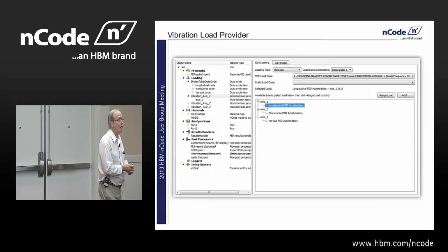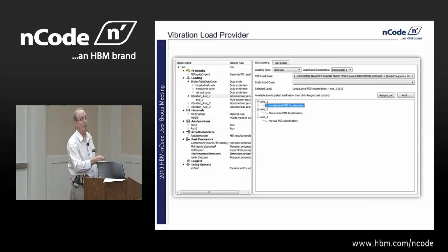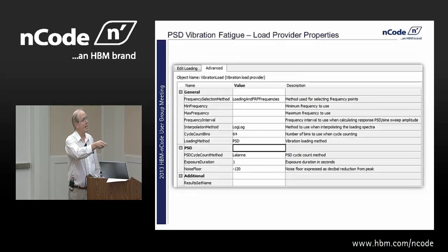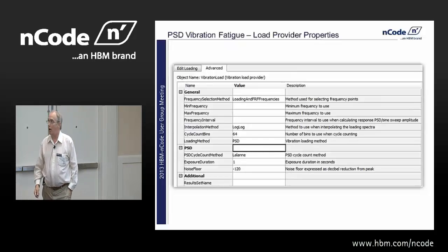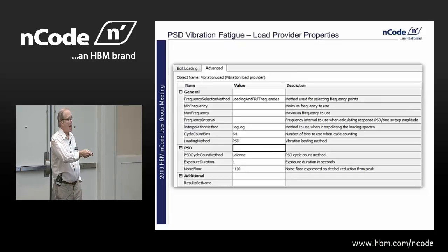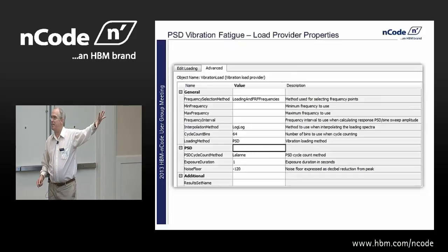So that all looks pretty straightforward, but there's another button up here. And the only way you can get to this button is to be in advanced edit. So in this particular load provider, even though you can see this portion of the load provider on the outside, you want to go into advanced edit. I rarely say that. So if I go in and pick that second tab, we see this. And so these are properties that are actually controlling the vibration load provider. And the first top portion here is consistent between both PSD and swept-sine.